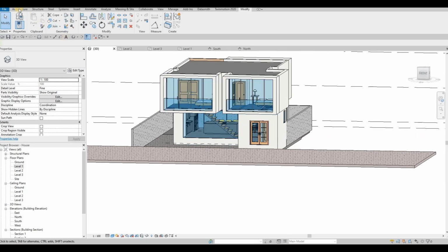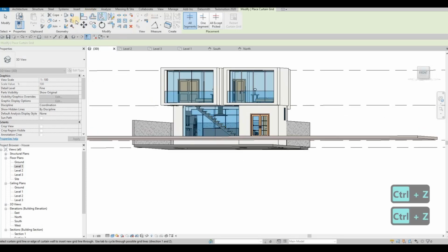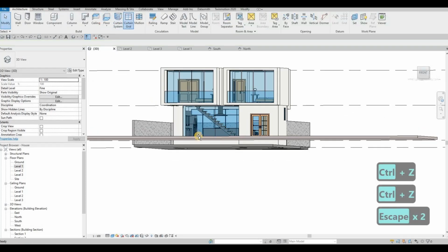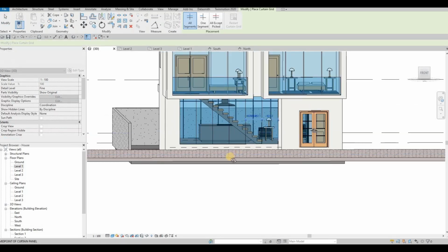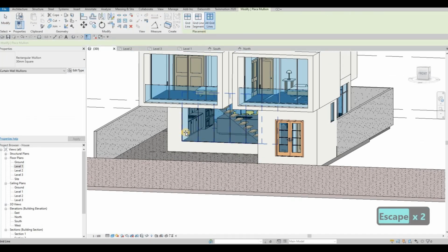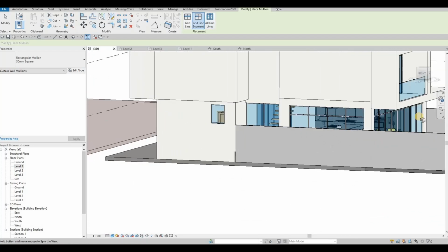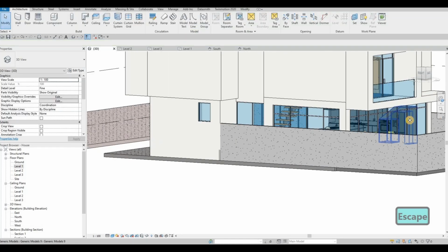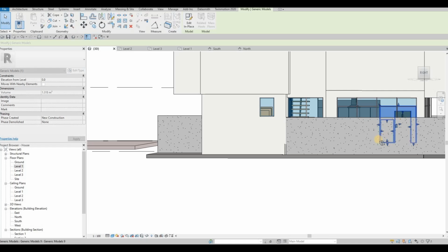We just need to have the curtain grid. I'm gonna make it even. Actually, there's more here, so I'm going to add 3 of a total of 6. And then just add mullion, and then there you go. Although this one got close up, we can then just edit this and make it something like that.